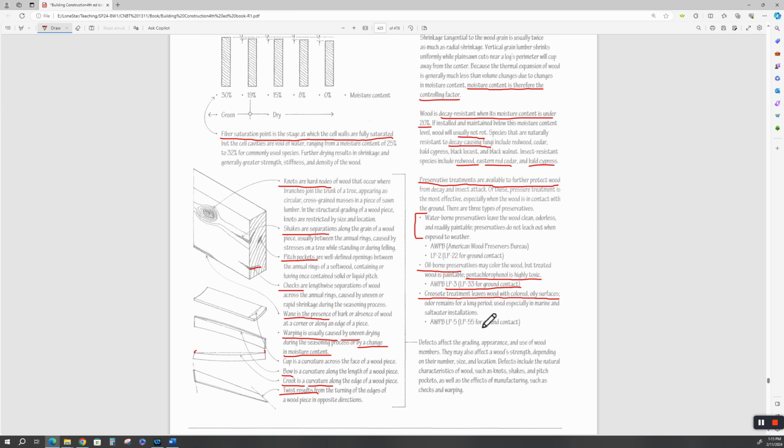Creosote is toxic, and you've got to be careful with it. And when it gets hot during the summer, that oil will leach out of that creosote pole forever. The creosoting is put in by pressure in a heated kiln-like thing. There's a big creosote operation up in Somerville, Texas, that specializes in railroad ties. They make railroad ties. All right. American Wood Preservers Association lists creosote as LP-55 for ground contact.